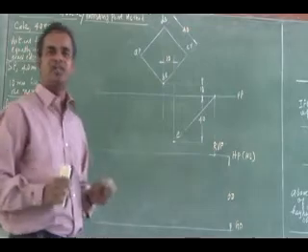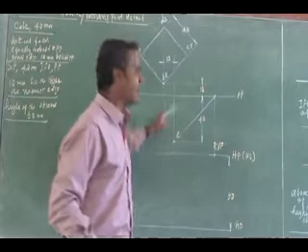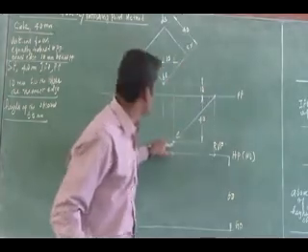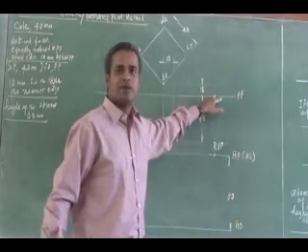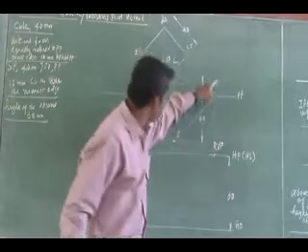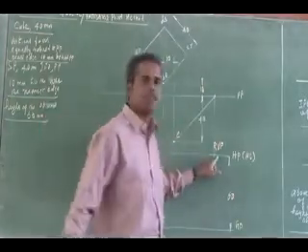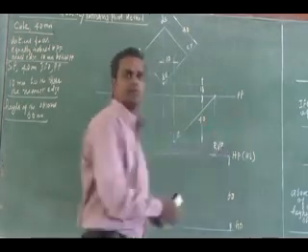So to obtain a vanishing point, first of all you draw a parallel line from the station point to one face which is inclined, get its intersection with the picture plane, then drop that, project that to the horizon line. Since my vanishing point will always fall on the horizon line, this is my right side, so the right vanishing point.